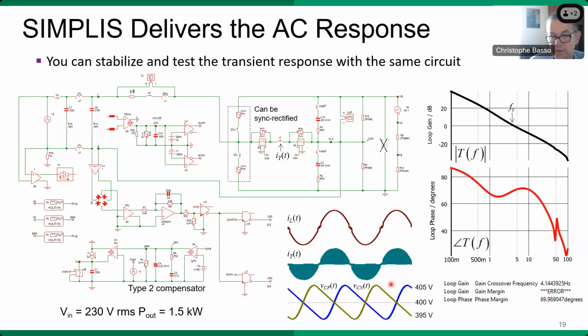So that's pretty cool. And you can see here the waveform and the envelope of the current and the 2 voltages with the split capacitor. One thing here, because you have two different rails, usually you need to have an extra low frequency loop that is going to work on balancing exactly the voltage between these 2 capacitors. So that's an extra burden for the designer, but you have to be aware of that.